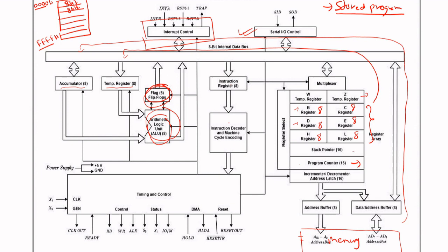Also, we have this stack pointer here. So the main task of this stack pointer is that the program execution might not always be sequential. For example, let's say that we start from this particular memory cell, and up to this line, the program execution is sequential. Then from this line we might introduce something like a call function, and that particular call function code is present in this particular location. So in that case, the program does not go down here. Now it jumps to this particular location, and after execution of this, the program has to go back to its last location to continue the execution.